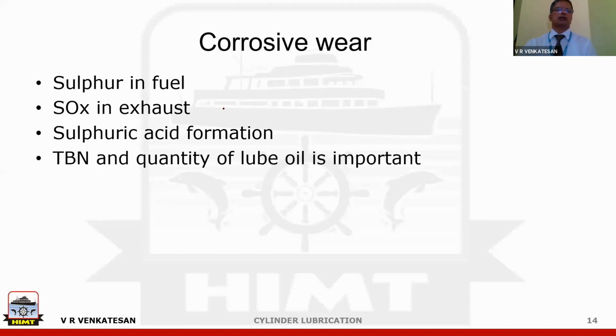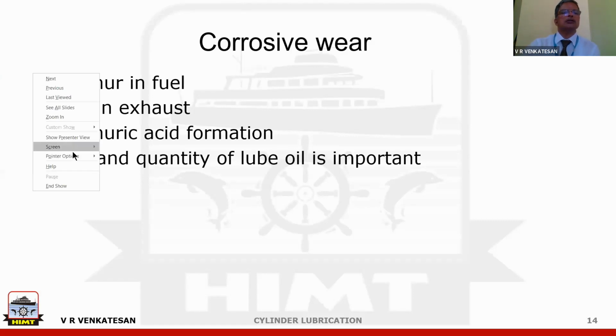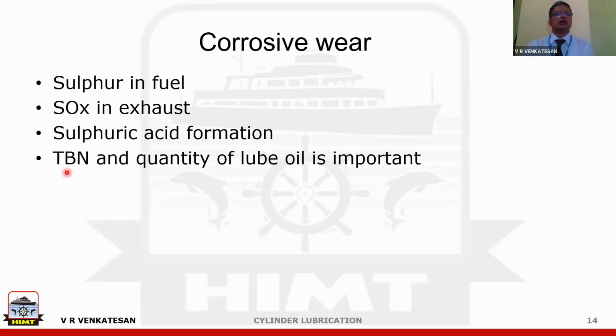So in this case, to prevent corrosive wear, what are the factors which are important? It is the quantity of lube oil again. But apart from quantity, TBN is important. If you don't have sufficient TBN, you will not be able to neutralize this sulfuric acid.